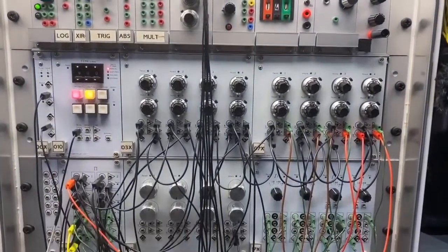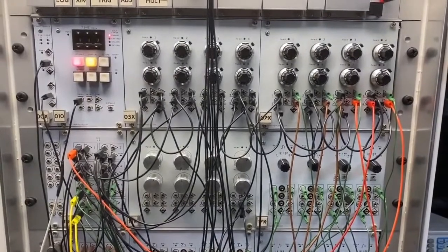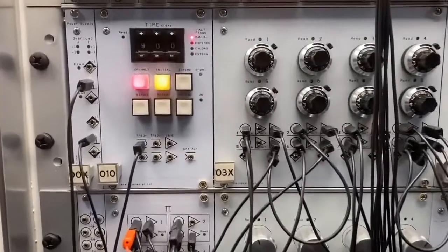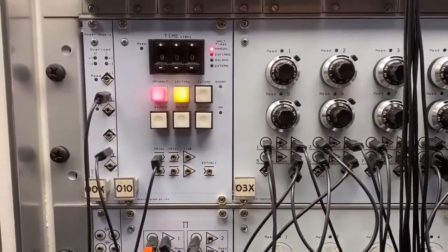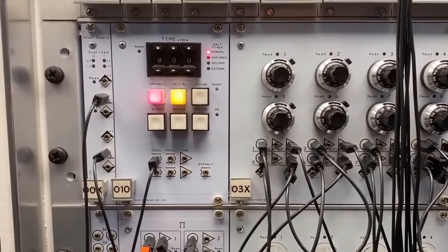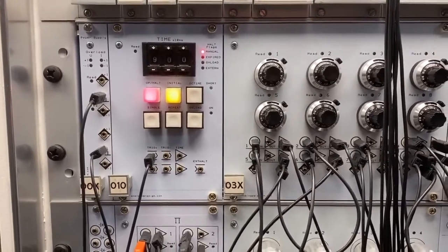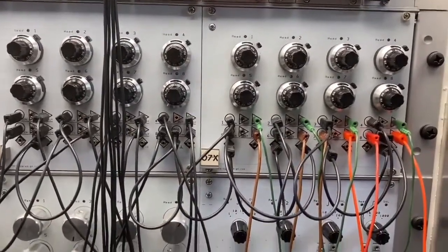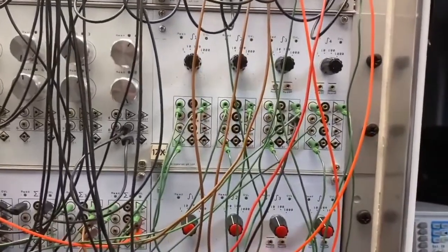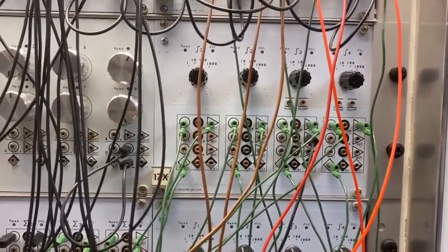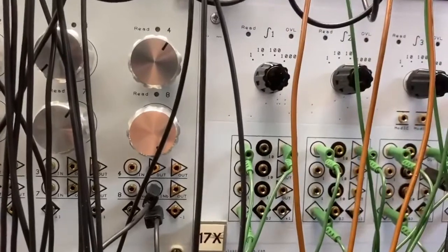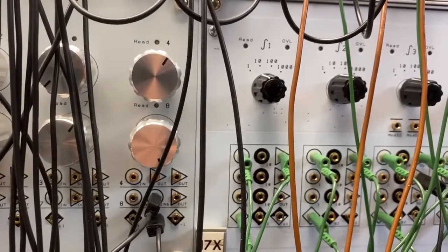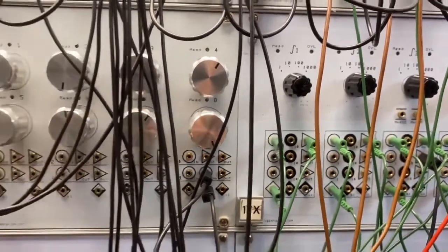And below, the chassis hold actual production modules. What you can see here, for example, on the left is the manual control unit. Here you can select how to operate the machine, for example, continuous operation or repetitive operation. Then you see 2 modules with 8 manual potentiometers each. The next chassis holds a quad integrator module, and you can see that you can set the time constants of the integrators, the time scale factors, in the range of 1 to 1000, as with the Telefunken RA770.